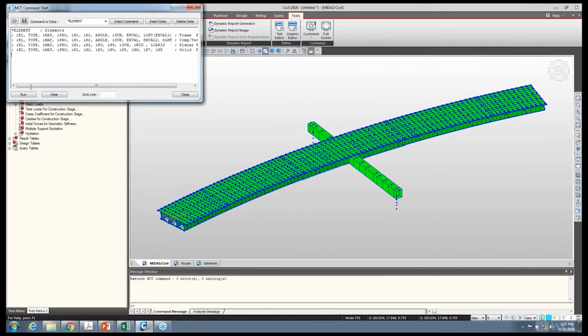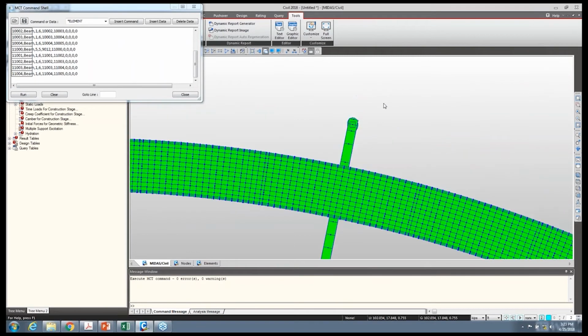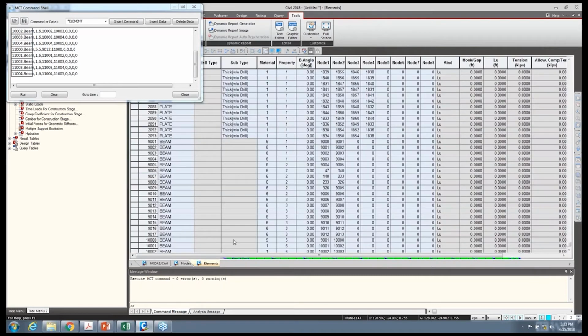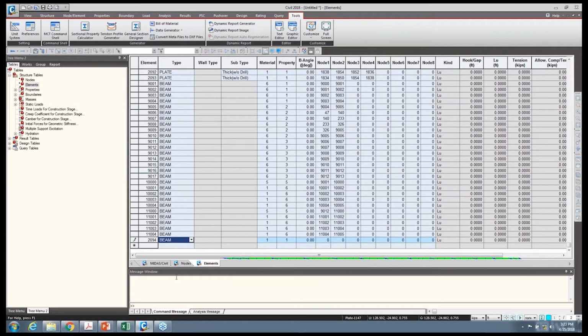Okay, that's going to create a little side node there that I need to delete. I apologize. So we're going to go ahead and revise these angles between our new column section. And so now, as you see, by just doing that quick adjustment, my column and my rigid link there are shown in the exact same plane as my straddle pier. All right. So now that we've done that, the only last thing to do is define our boundary conditions.